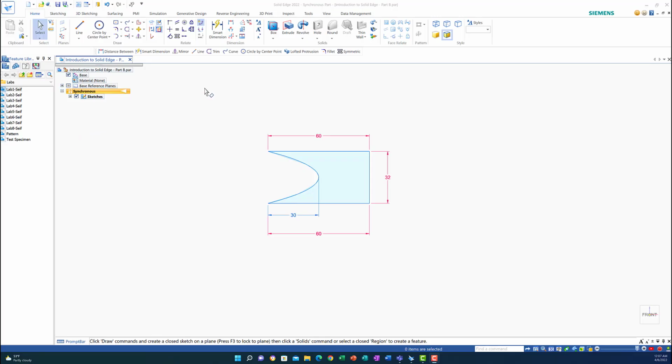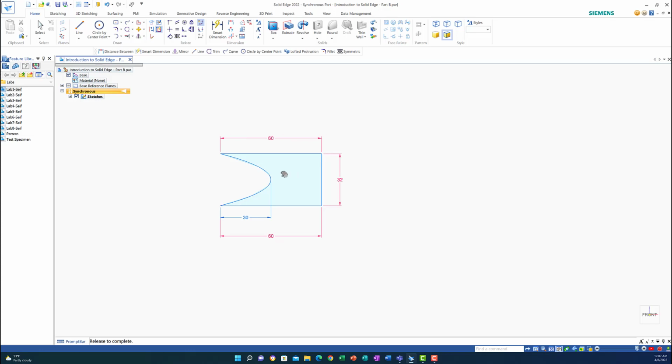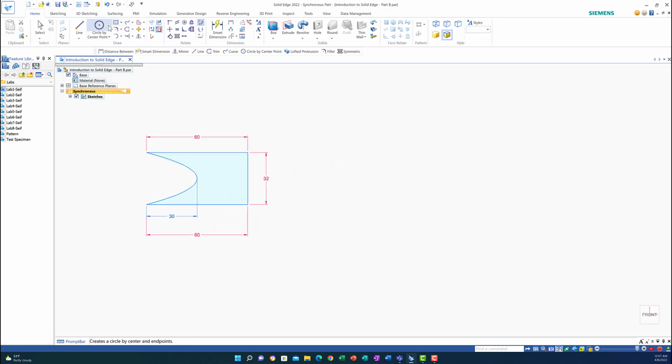The coming example will show you how to use the Conic command to draw Rosetta leaves. Okay, so let's go to Conic. Go under curve. I'm going to choose Conic, and let me move this one to the side. I'm going to choose a point.